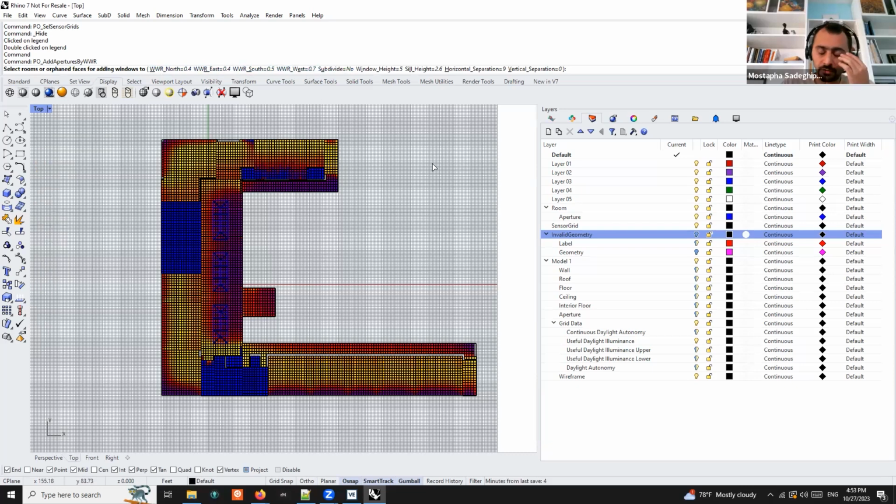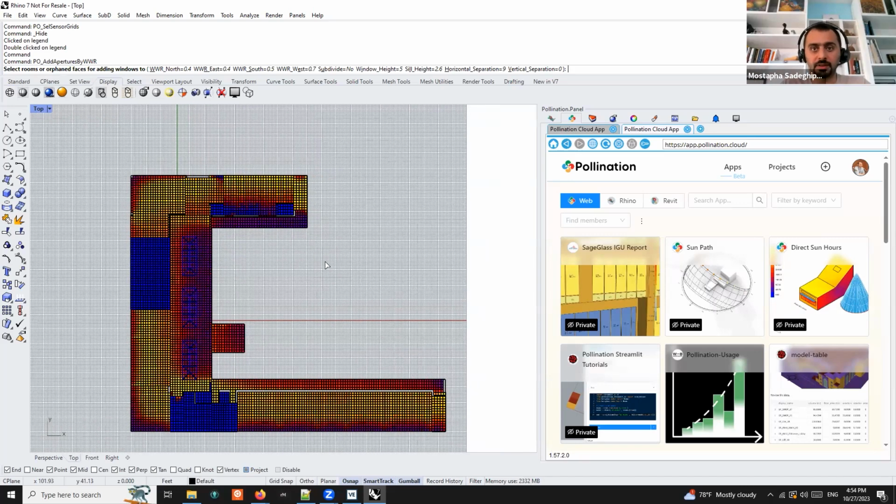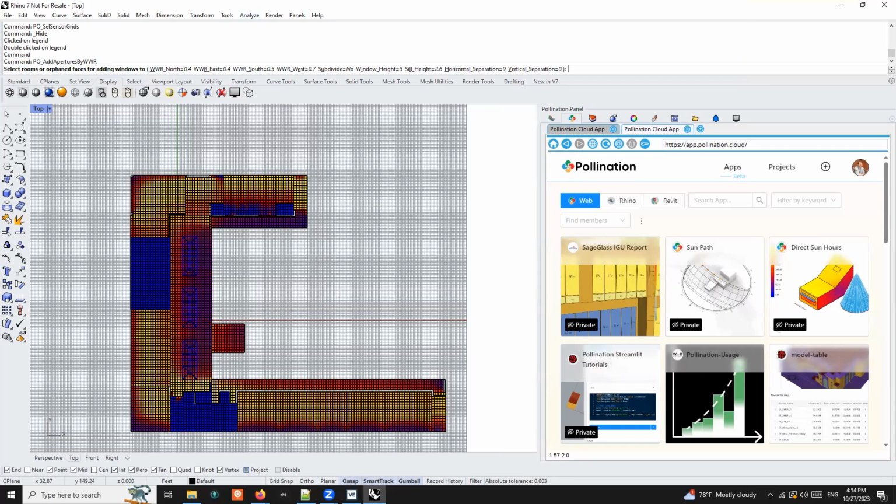That's one of the improvements that I want to have next year: we have some project data, so every single time you don't have to go and select the location and weather file. Just set it once, similar to how Revit is, for example. Then all the weather data, north, all that information is tied to your project. So we know what the weather file is, we know where north is. That should give more flexibility. But right now, we mostly assume the model is set the way that it works, and then you change the north input for your simulations, at least for window to wall ratio. Yeah. Okay, thank you.